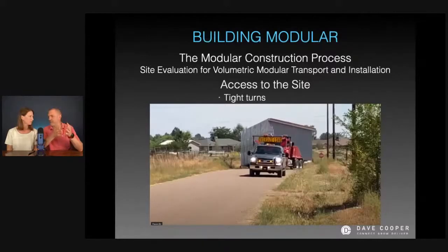Now, Jen, if I got stuck on that corner, what could I do? So this is where you do want the equipment, right? Where you may want a bulldozer or something else that can help you, maybe just give it a little tug or a little push. Well, yeah, if you use a front loader, definitely want a wheeled vehicle on the road, right? But a lot of times these units are pretty stiff. You can use a front loader with some forks on it, get underneath and move it over just enough to get it through. You're not wanting to lift this thing way up in the air, but there are tricks to the trade to this.